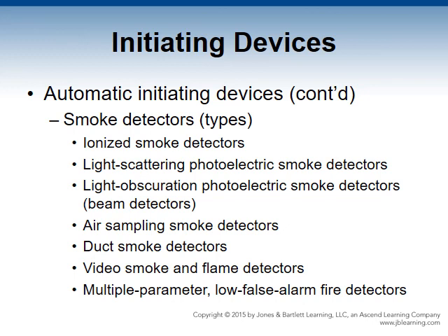They can be hard to see from floor level, so their location must be documented and clearly identified. NFPA 72 requires some to have remote indicators. Adequate access to these detectors for maintenance and replacement post-incident is necessary to avoid false alarms or to perform manual resets if there is no remote.